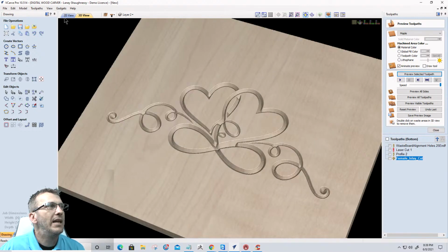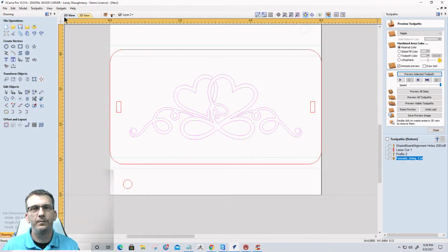All right, so now when it comes to creating the male, I don't need to cut the male out of a 3/8 inch piece of material. I could, but that means there's going to be some waste, right? And it's scrap wood anyway, unless I do a gang of these boxes out of a long board, just cutting a whole gang of them up for a production run or something. But if I'm throwing my one-off scraps in here, I don't mind if there's some waste that's going to get milled away when that male gets milled off, the waste area gets taken off. But I would probably carve the male out of maybe a 1/4 inch thick material so that I don't have a whole lot of waste, or 3/8.